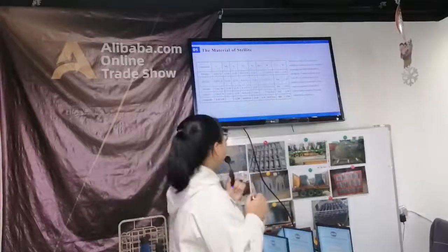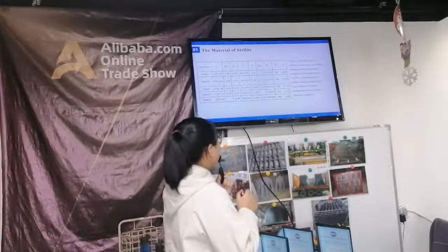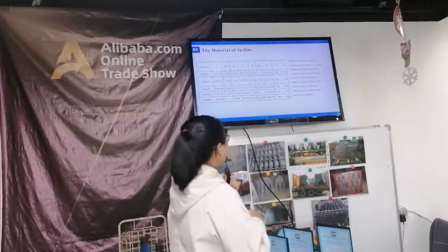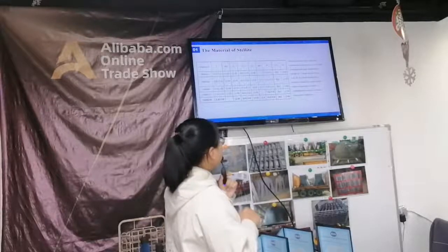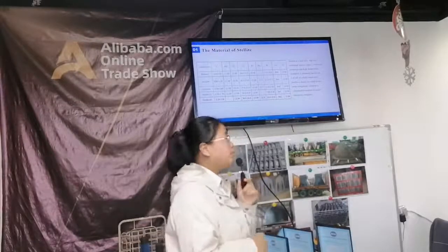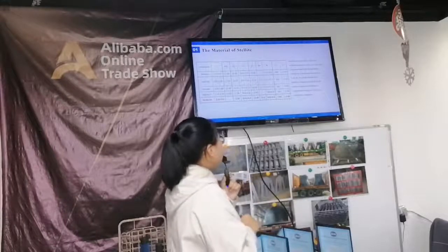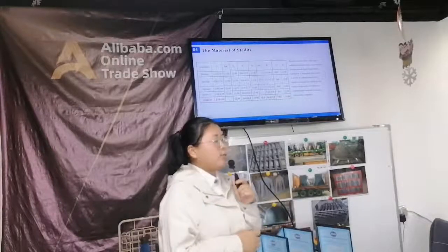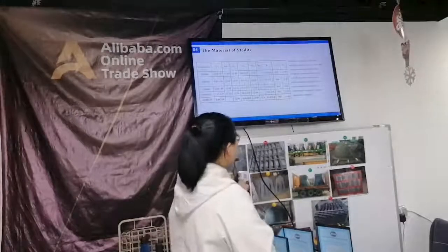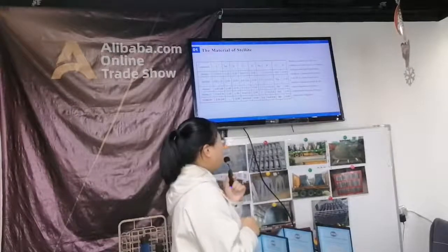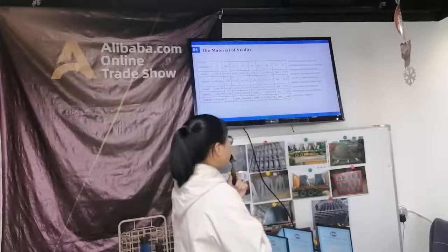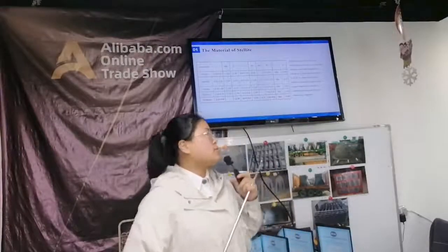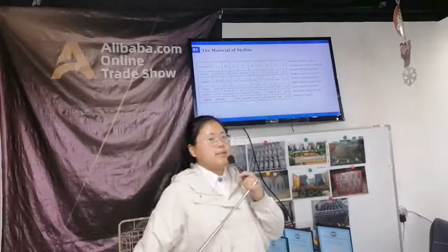Stellite 4: carbon is 0.8 to 1.2%. Manganese is less than 1.0%. Silicon is less than 1.5%. Chromium is 28 to 32%. Nickel is less than 3.0%. Tungsten is 5.5 to 15.5%. Iron is less than 3.0%, and the cobalt is balanced.